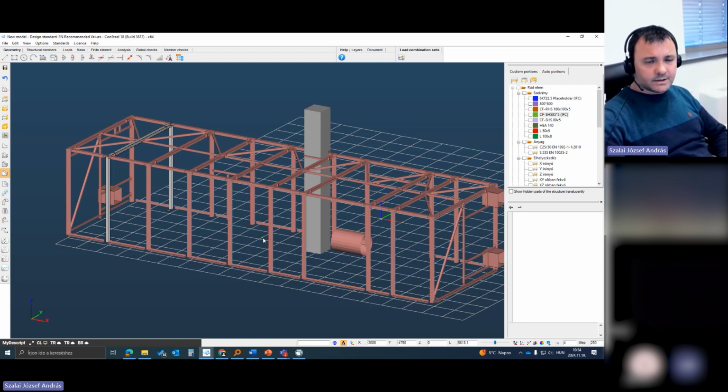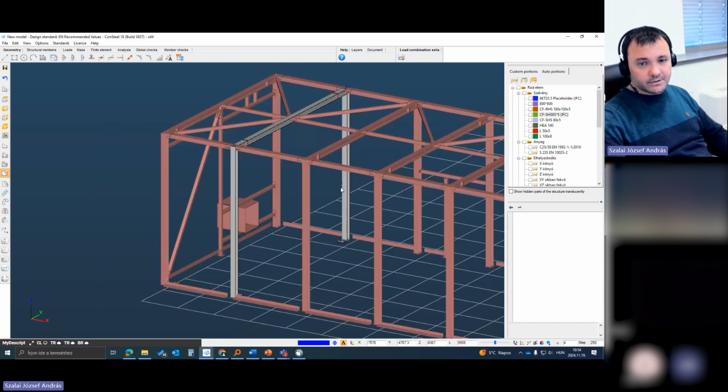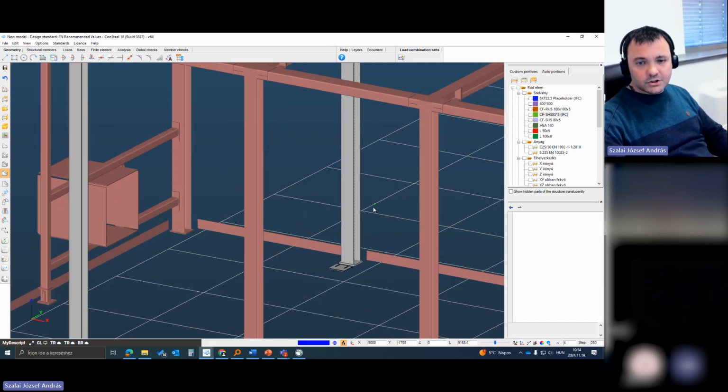The boundary representation cannot be used for real structural elements, so we cannot turn these objects into structural members. We just, for example, take this frame as a boundary representation in IFC. These are just two-dimensional figures in separate layers.